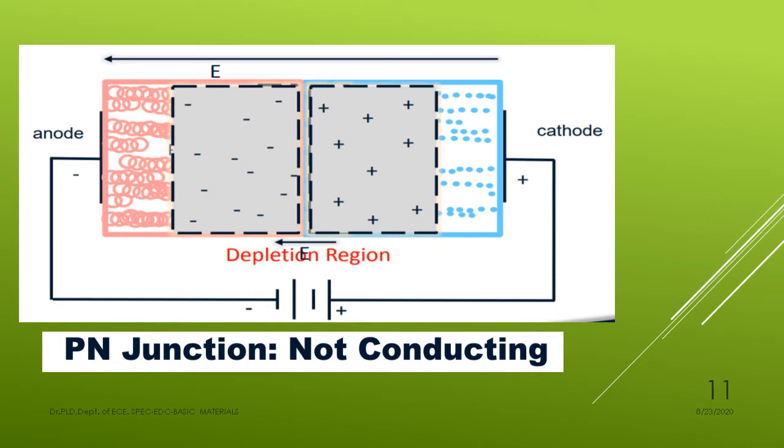Because of the increased depletion region width between the P and N type semiconductors, it allows a very small amount of current. But you may have a doubt in this case: there are minority charge carriers also, no? Yes, there are minority charge carriers. Because of those minority charge carriers only, some amount of current passes through the junction. That particular current we call the reverse saturation current.